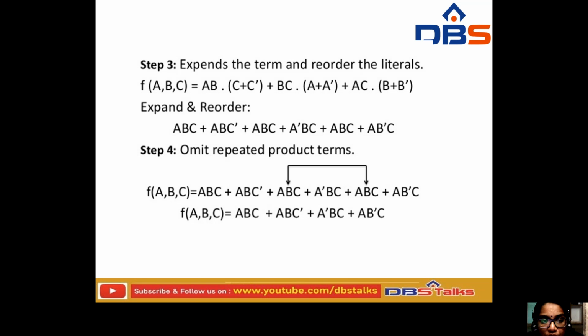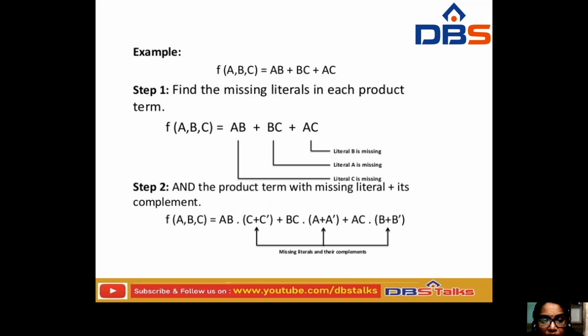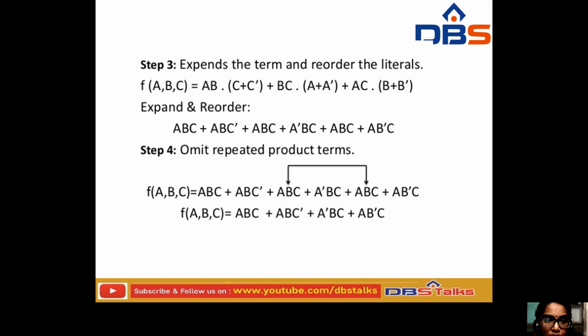This is the expression that we have converted into the standard sum of products. Okay, this is how we are going to convert the sum of products to the standard sum of product forms. See here, in step 3 we have expanded this one and we have reordered the literals. After that we have checked what the repeated product terms are, and after checking that we have taken out the repeated thing, and finally we wrote the expression like this.